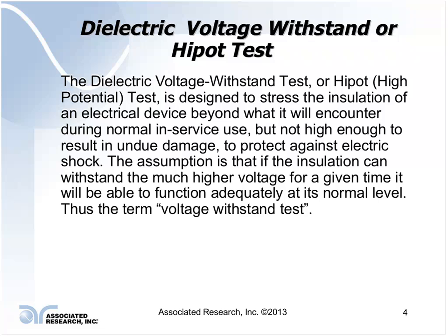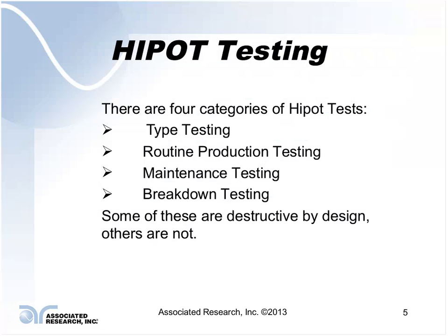The insulation itself is based upon the operating voltage and the pollution degree: is it meant for indoor use, outdoor use, what kind of environment. All these come into play when we're talking about the electrical insulation of a product itself.